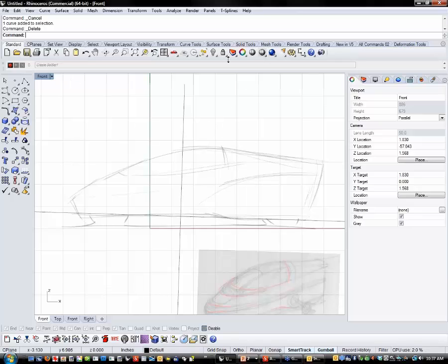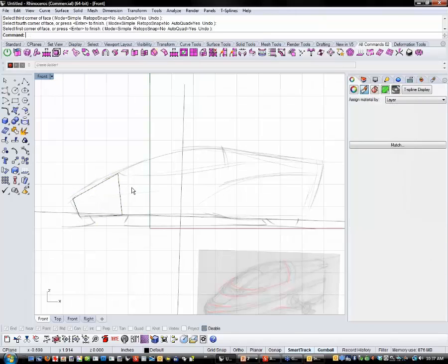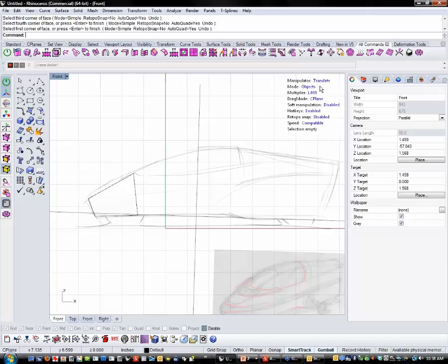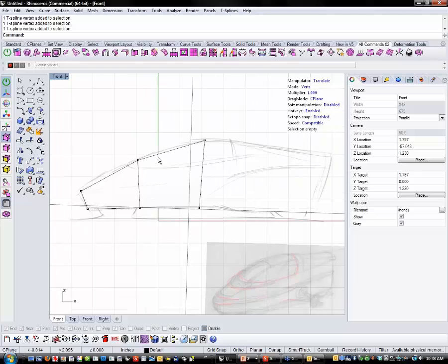patches and T-splines. If I go up here to my append face workflow, and lay out a single face in here, and I bring up my object, and I go to edges, and I alt drag, shut the Rhino gumball off, shut the smart track off, and I just alt drag. I'm going to do this in box mode. I can put 1, 2, 3 points there, right? And ideally, I may even want to do this because, simple, simple, simple. We want to start as simple as we can and then add only where we need to and when we need to. So if I smooth this out, you'll notice that I get a nice arc. See, 1, 2, 3. That's all I need in order to get that shape.